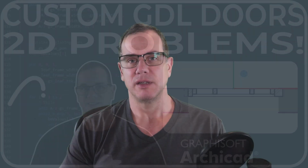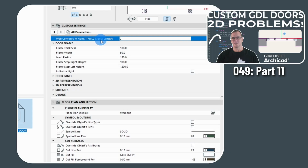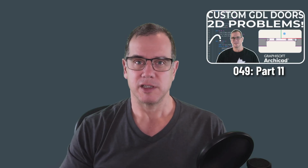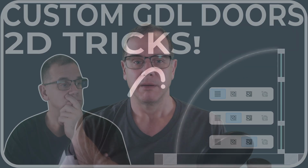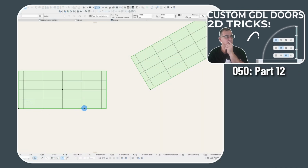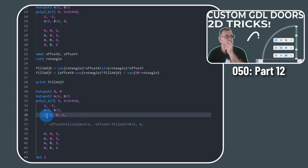Episode 49, I touched on the default contour lines that come with the door object and rearranging your logic to suit your developing script. Inline logic conditional statements, so that's an if statement but without the if, and other 2D scripting tricks. There's some good tips wrapped up in this one. Episode 50 talked about setting the origin and orientation for fills in 2D using the poly2b2 and the poly2b3 command and what the differences between those are and which one you should use depending on your situation.